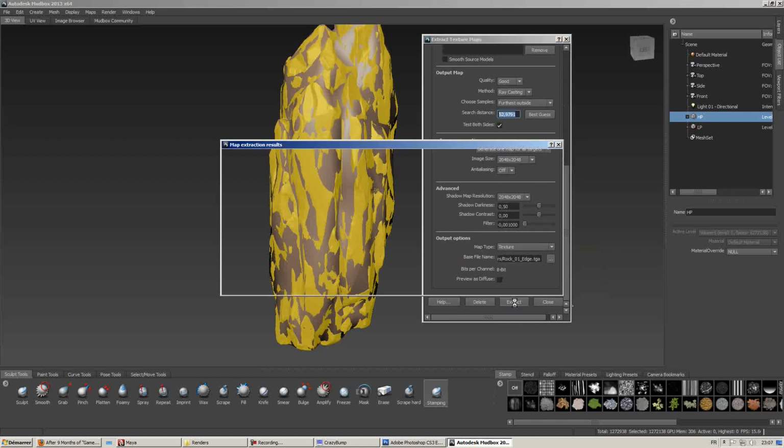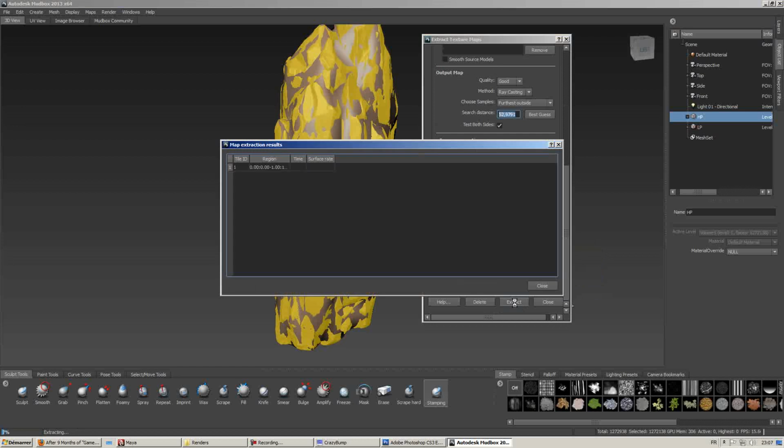extract. The rendering should take a while. If you turn on anti-aliasing, that's really going to pump up most of the time. Rendering time is going to increase exponentially. Instead of taking like 2-3 minutes for rendering a texture map, it will take you like 15 minutes or maybe higher, and it'll make your computer completely unusable during that time. So be careful with the anti-aliasing settings.